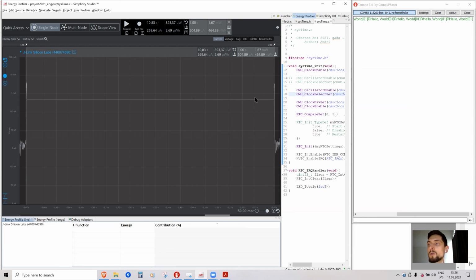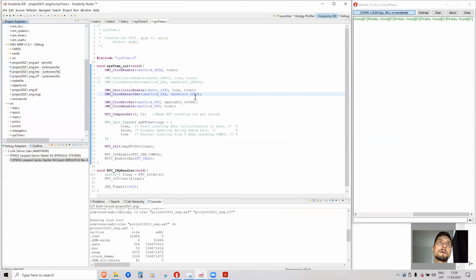And the second part of your practical lab work is you do as I did by selecting a low frequency external oscillator and repeat the experiment once more: put the development kit in the freezer, and then after an hour, attach it quickly to your computer and measure the time. And then put it in sunlight or next to your computer's fan, or try to warm it up in a different way and check out the frequency. Then just don't break it.